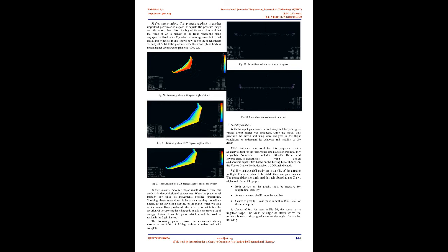These dimensions are defined after thorough analysis through iterations and introduced as flaps into the foil. Being a fixed wing, there are no elevators and fins, thus an aileron is used for horizontal stabilizers. Winglets are used as vertical stabilizers in this flying wing UAV. The winglet is of blended type with an angular transition. Final dimensions of these stabilizers are mentioned in section 7.